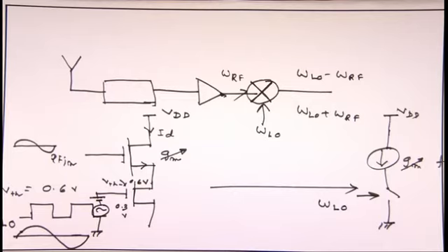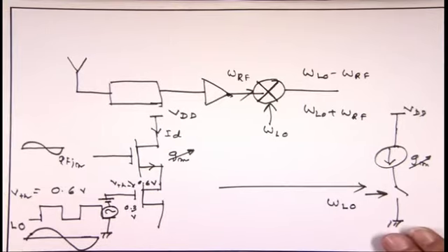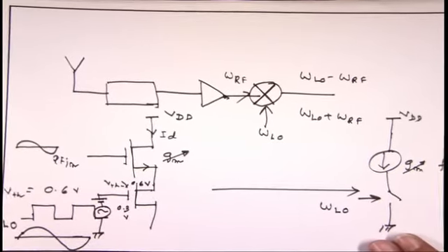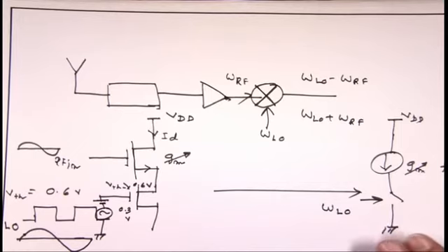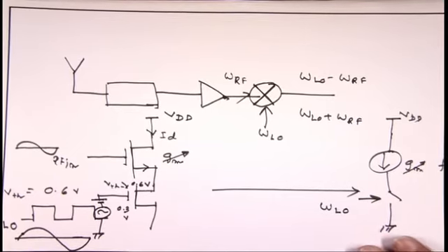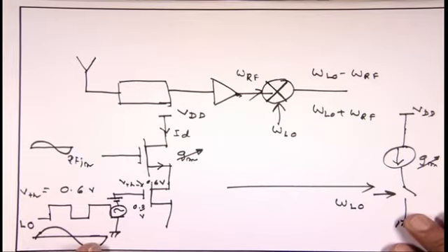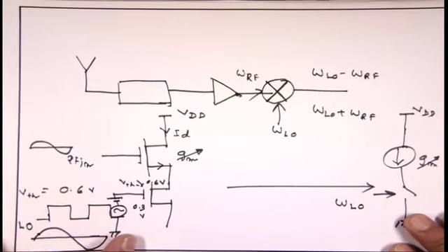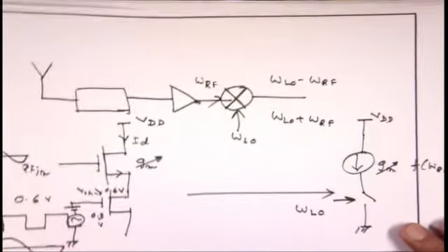So, that is the multiplication, when two quantities A and B are multiplied, both of them are changing each other and giving a resultant. So, you have a transconductance variation based on your RF in, and then the changing current is now being switched by an LO signal. So, you are getting an output which will be a function of both omega RF and omega LO.